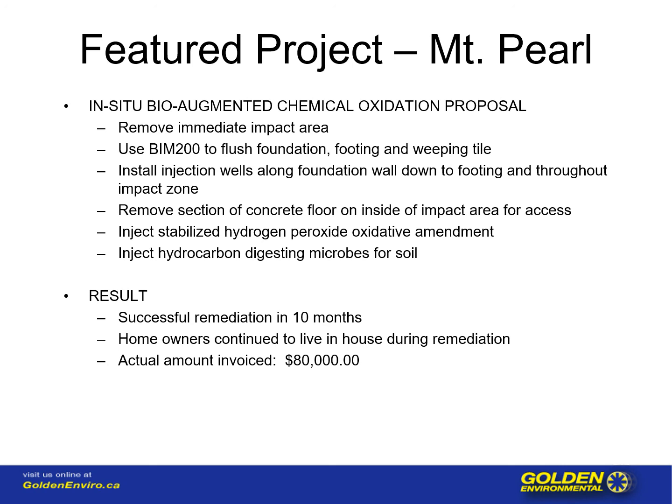The reason that we do this bio-augmented approach is to re-establish the hydrocarbon digesting microbe count in the soil so that if perchance there is any residual, they will continue to do the work. The result was successful remediation in 10 months. The homeowners continued to live in the house during the remediation process, and the actual amount invoiced was $80,000.